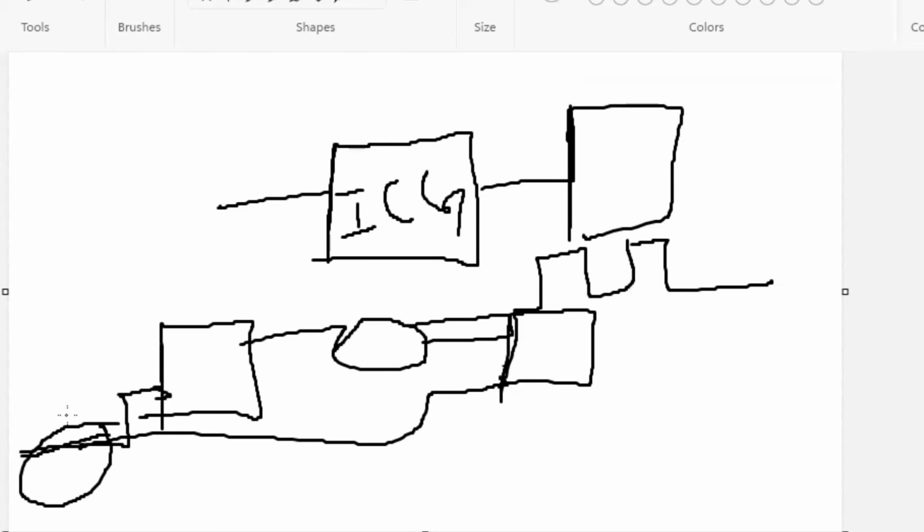My chip should be operated at Hyderabad as well as in Himachal Pradesh, right? So we are giving the worst conditions so that while implementing itself we can close the timing at these corners.